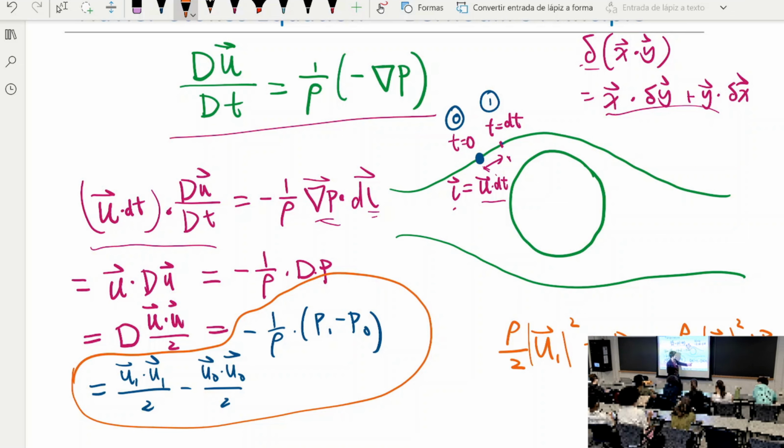Highest over here, right? Look at this: velocity squared plus pressure is constant, of course, times half rho. So velocity being minimum here, equal to 0, means pressure being highest over here. Velocity being highest over here means pressure being lowest over here. It's going to be the same for airfoils. Whenever we have high velocity, we have low pressure. Whenever we have slow velocity, we have high pressure.